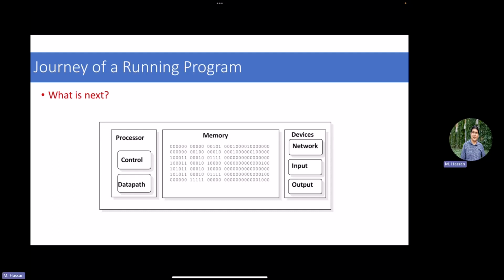So another question here. If I do what I'm doing right now, by all the time increasing the program counter by 4, I am overlooking my program, right? Because the sequence of the program is not all the time you execute one instruction after the other, right? So there are other cases. What would be these cases? Yeah, a jump or branch.